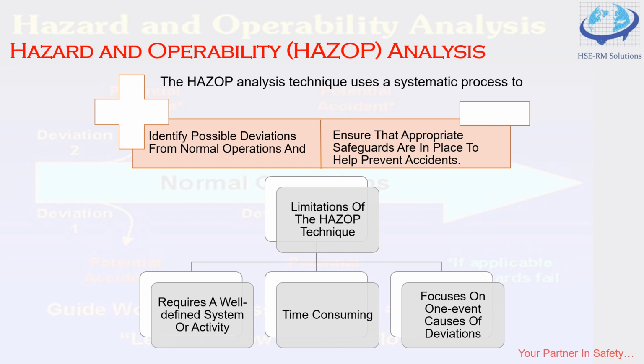Here the team is applying a qualitative approach to analysis, theoretically discussing possible consequences that can go wrong if the desired action is not done. Now combined with the process conditions, which can be defined as speed or flow and pressure, to systematically consider all credible deviations from normal condition. Now for each guide word that we use, we discuss specific conditions that can arise, and finally control recommendations are taken into account.